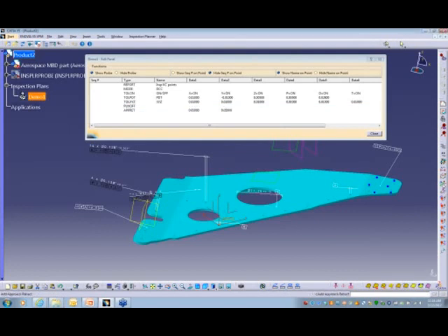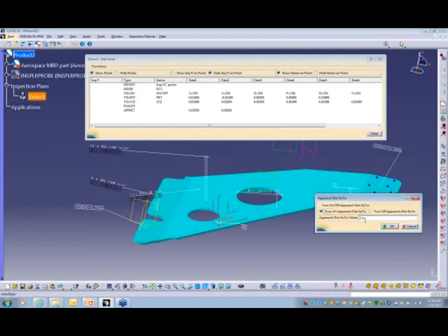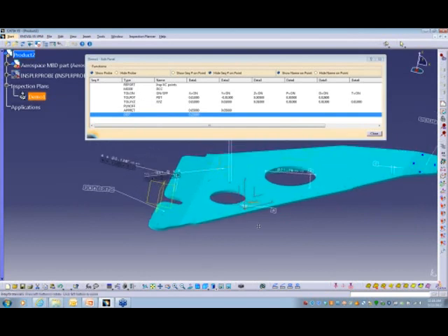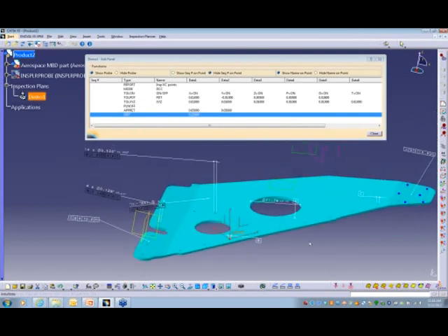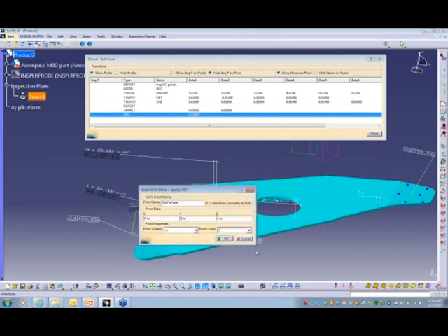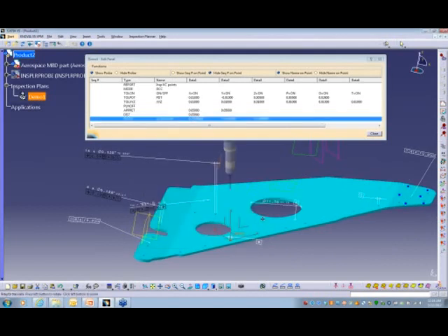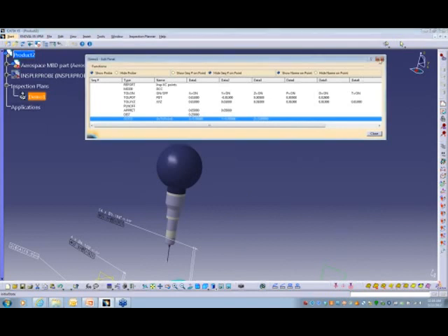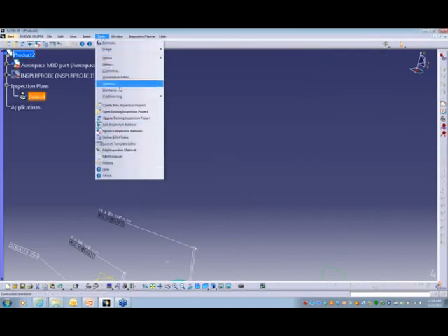And we'll also put, oops, hitting the wrong button. We'll also put a go-to move into the program, and we'll set it at 1/4 inch every time. It comes in part or it takes a point. So all this information is setting up how the motion of the CMM is going to work. And now we'll put a start go-to move in. So we'll go to 003. So now we get to see the probe. Going back to that, we can see that the probe is built.